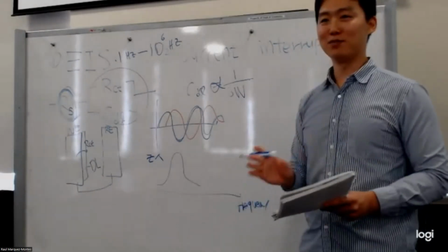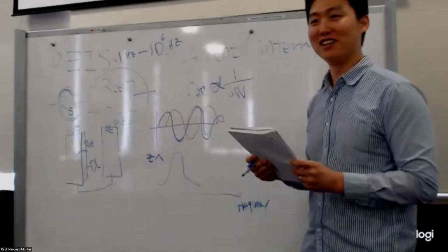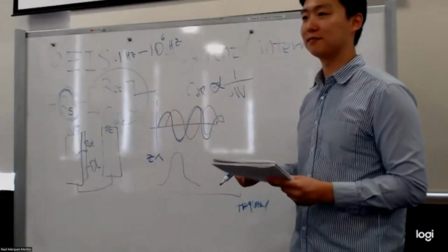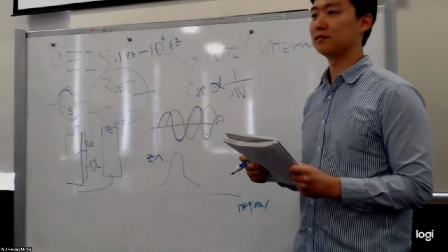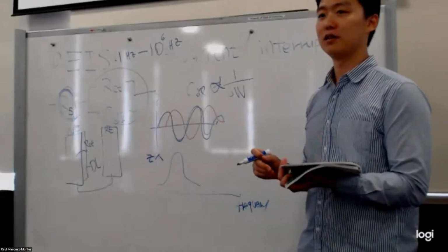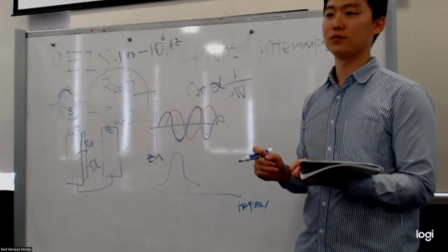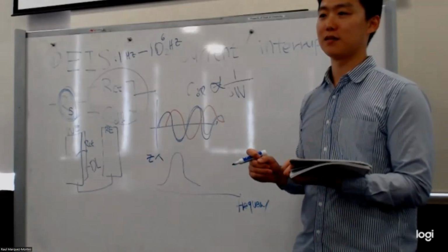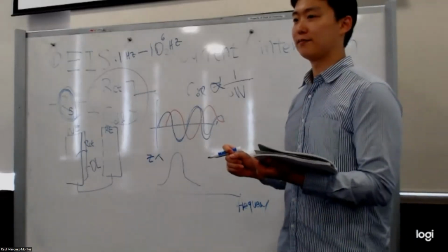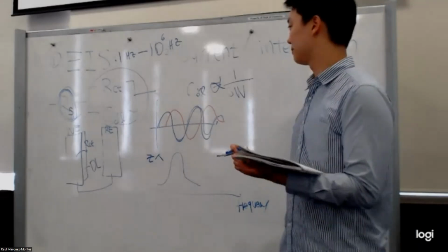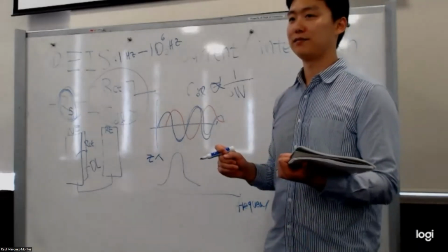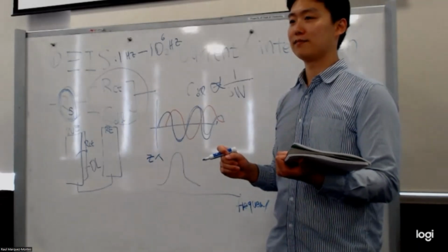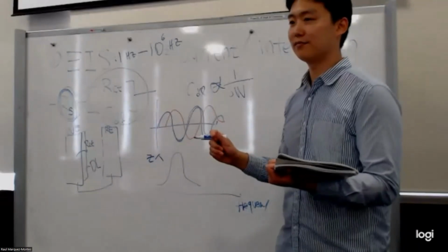No, actually, I skipped many explanations to make it simple. Yeah, the charge transfer resistance is coupled in with that capacitor because of how it's set up in the circuit. So you apply that equation to fit that Bode phase plot, and there's normally a very clear development, and that resistor and capacitor fit that part, and the other resistor will fit the second development in the plot. Okay, so it is pretty separated in the plot.